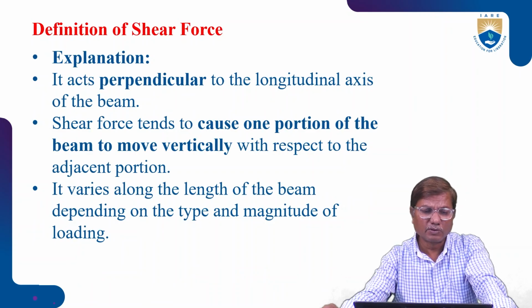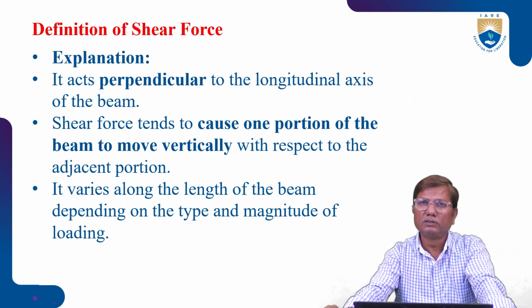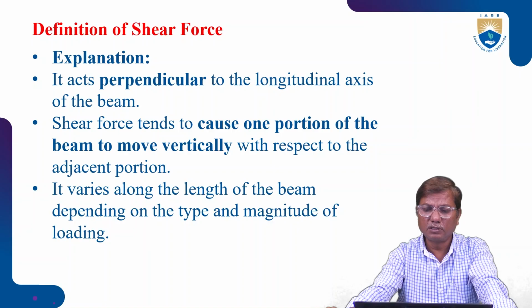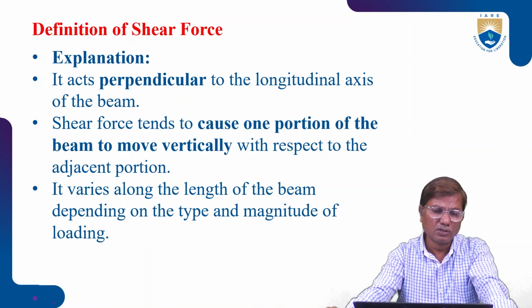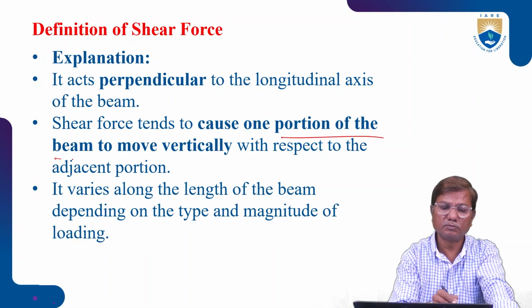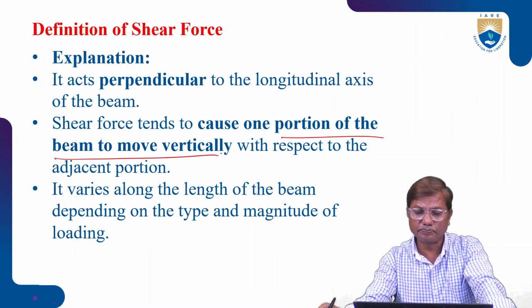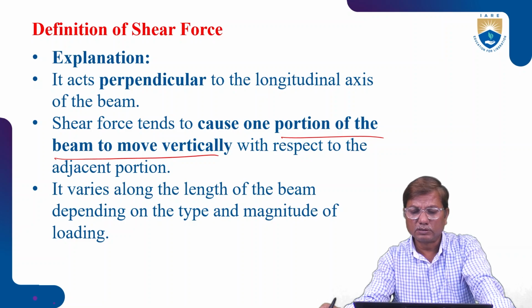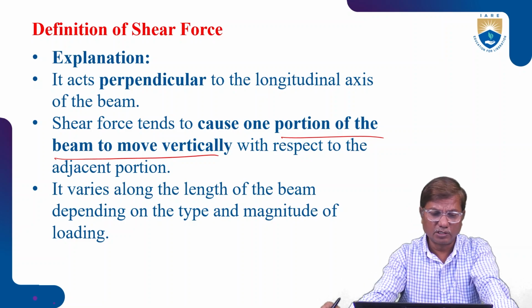The shear force is perpendicular to the longitudinal axis. That means it acts in a transverse direction, perpendicular to the axis, that means parallel to the cross section. Shear force tends to cause one portion of the beam to move vertically with respect to the adjacent portion.